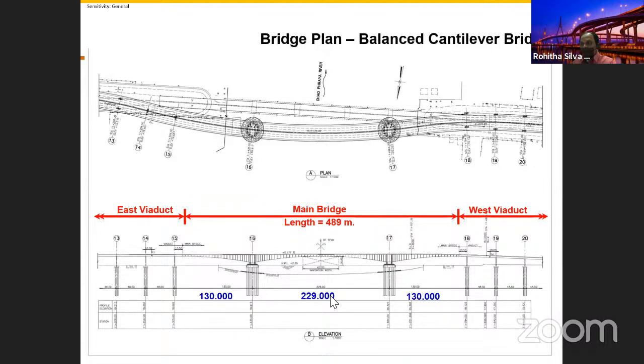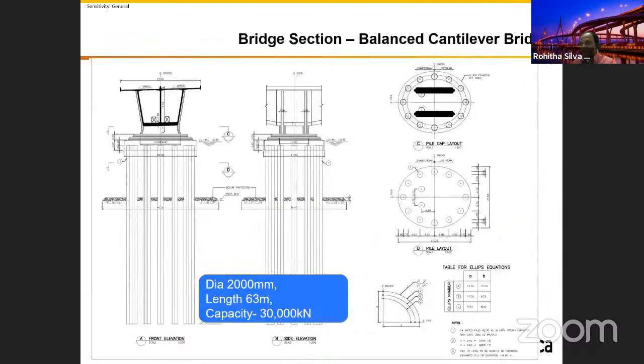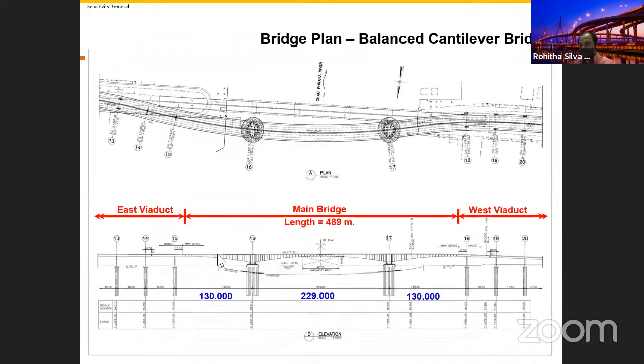This bridge, when you are building it, is not going to be easy. We had to build this one across. You can see in the middle of this bridge, there is a 60-meter width. Sorry, I didn't put that number. There is a clearance. This 60-meter width and this clearance we need for navigational requirement, because on this bridge, the Chao Phraya River, they use a lot of boats. They use the boats to transport things. Because of that, you need that clearance requirement.